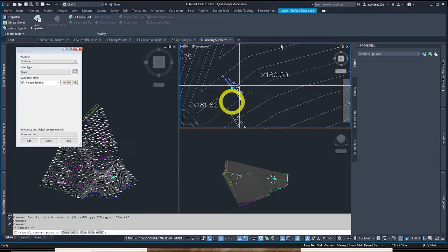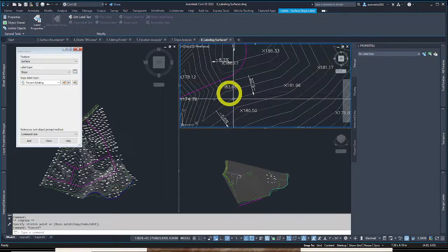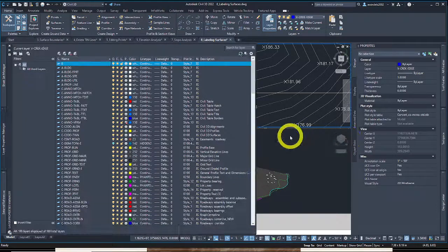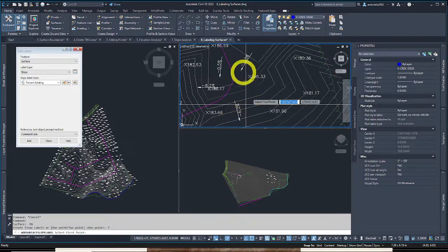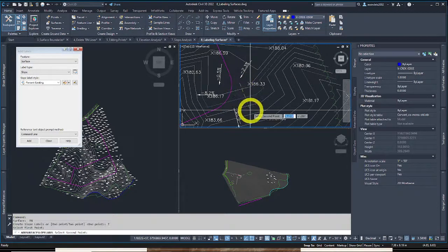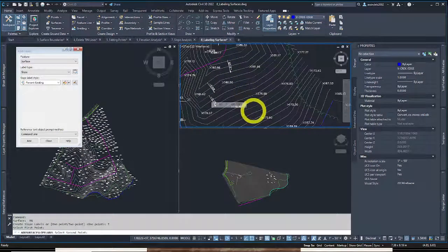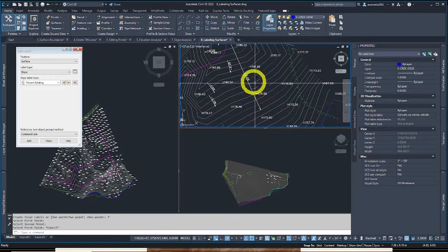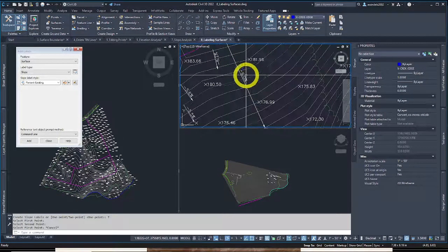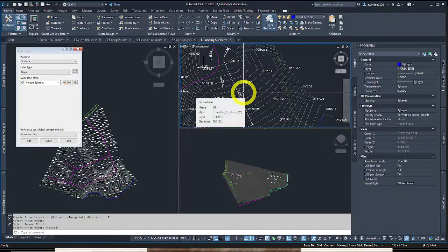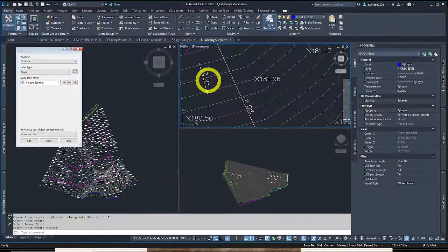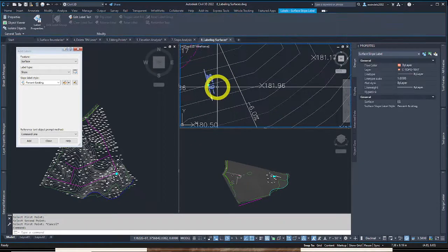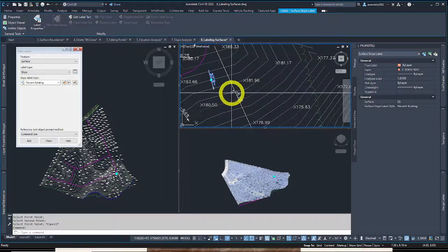Now, if we did a 2.1, you're making it a little bit fictitious. You select its 2 points where you want it to go. We'll say add, go to 2-point instead. It wants to default to 1-point, which is great. Usually that's what you want. Let's just force it to pick there, and we'll do a second pick here, making a really long one. That's -6 downhill slope there. Negative always means it's going in the downhill direction, and these 1-pointers always default in the downhill direction because that's usually where we want to see water flow.